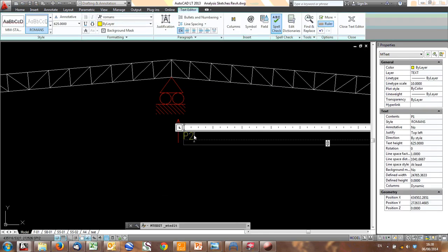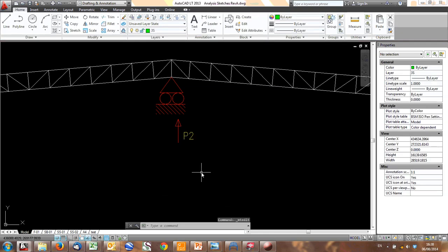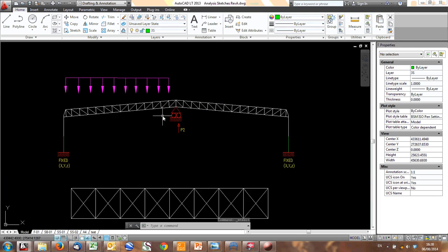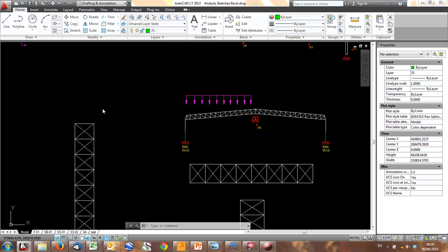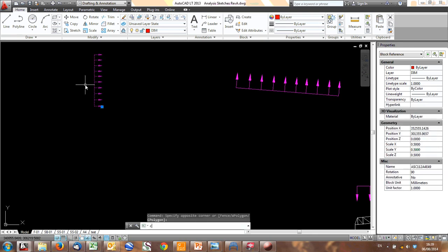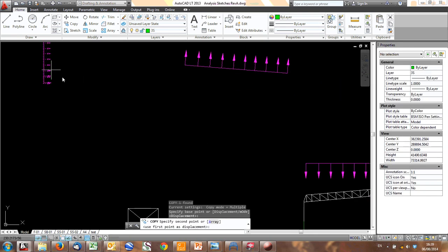And once again, we must ask the question, where does that load go? It's due to the girder, but let's first have a look at this whole frame. There's something else that might be an issue. If you look at this frame, it's not that stable. How are we supporting it horizontally if you've got a big load? Take a load here. And you push it across.